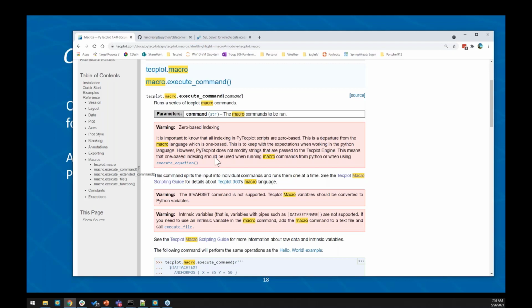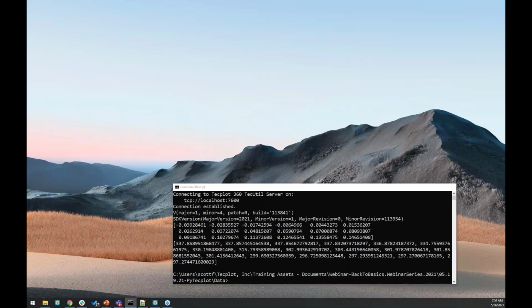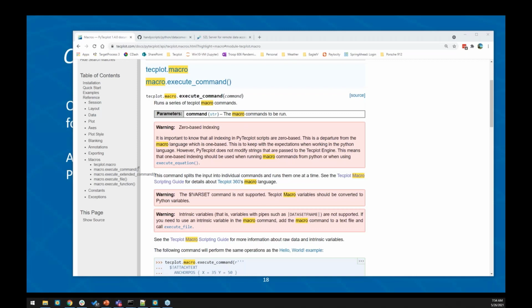This question is pretty new. Can I add to a 3D plot simple XYZ data, say from a text file, to just plot location points on the existing plots? Yes, I think this is basic Tecplot functionality which you can do. And what you can do in Tecplot itself, of course, this is scriptable too, I would say.